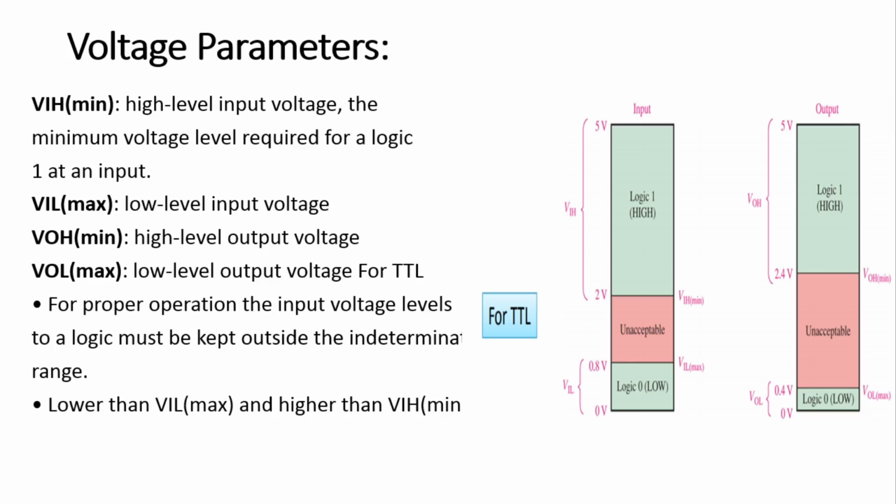For proper operation, the input voltage levels to the logic must be kept outside the indeterminate range: lower than VIL max and higher than VIH min.